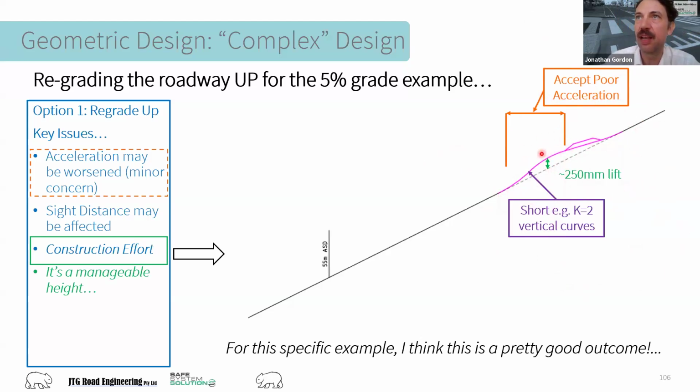And if we were to put this larger 13.8, this becomes significantly larger, and I actually drafted it up. I won't be presenting it today, but it's around about 600 millimeters. And that's the difference between full reconstruction over, say, 80 meters versus a relatively compact system and an overlay solution of, say, 250 millimeters lift, maybe some reconstruction, or you could have that as an asphalt overlay.